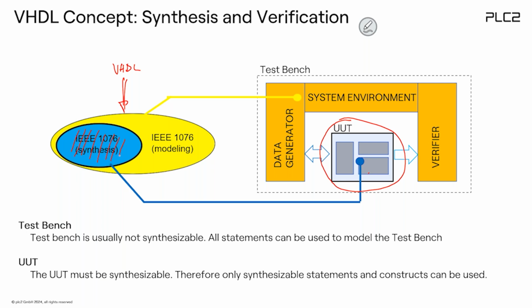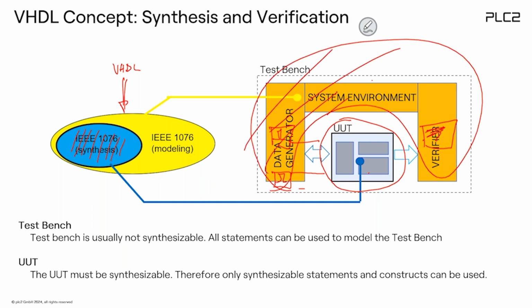But now we need, of course, to run the simulation. So we need maybe to describe an oscillator, or a reset generator which resets, or maybe I would like to observe the signal by having a model which receives the stuff. So the environment, but this environment I will never synthesize, never. This is just for checking the function of my FPGA. So in this case, I can use whatever I like. I will never synthesize this. I will only synthesize this. So this is your job, to understand which is synthesizable and what is not synthesizable.